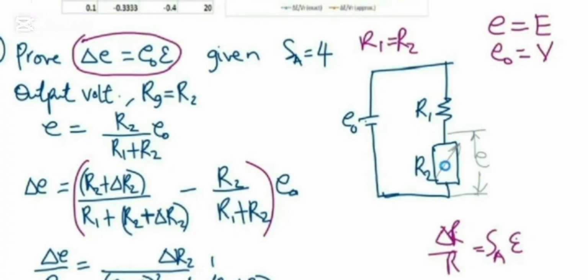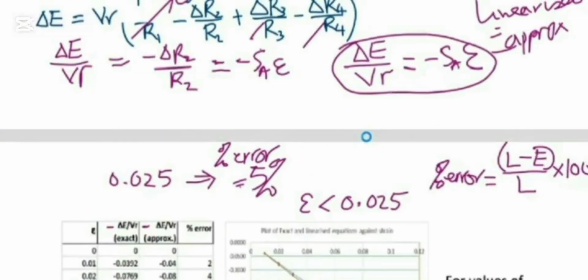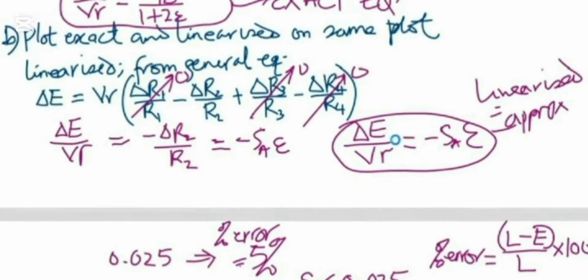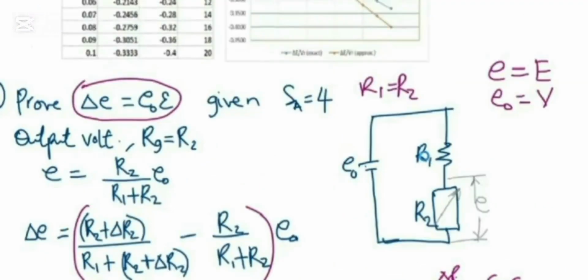Strain. After the loading, you pick the strain gauge and place it in either a potentiometric circuit or Wheatstone Bridge circuit to be able to determine the output voltage, from where you can determine the what? Strain. And R is what? Is the circuit sensitivity. While SA here is the strain gauge what? Sensitivity.